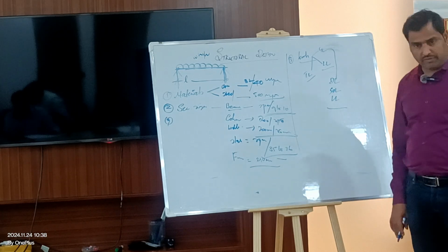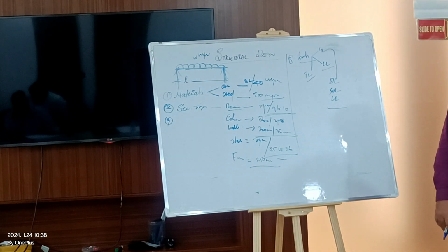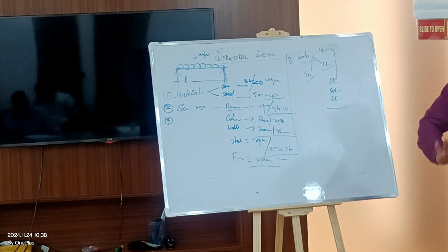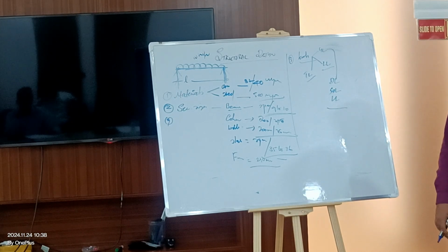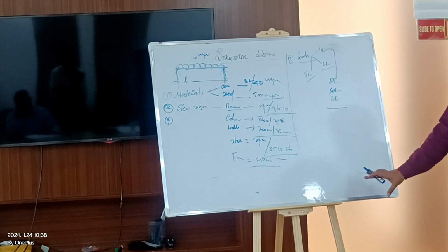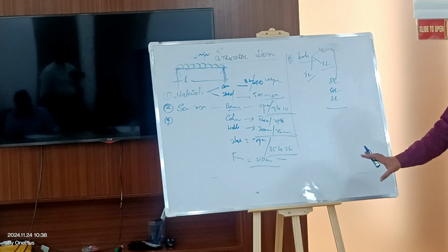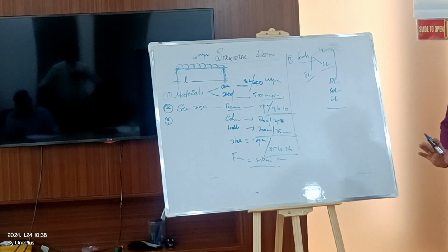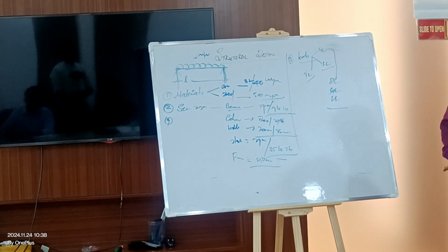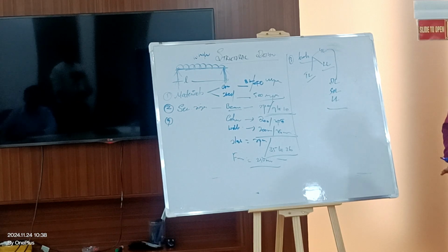The pile we will discuss further, when we are going to do this. I'm only talking about the foundation thickness. Either it is isolated or a raft foundation, the minimum thickness you have to follow as per codal recommendation is 25 cm. But practically I can only go for 30 cm. Even for villas you are going for raft foundation, right? If there is a basement, what do you do? You cannot go for isolated foundation if it is a basement. You need to go for raft foundation.